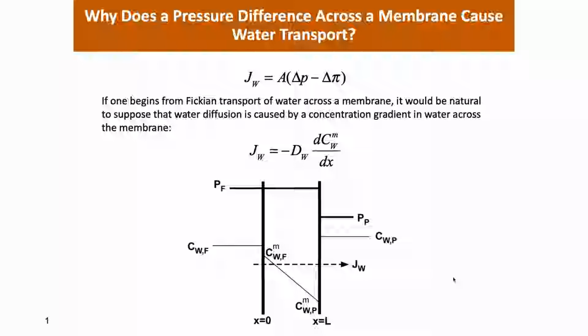And so there was the rise of a theory for reverse osmosis, or in general liquid transport through what I would call non-porous membranes, that was based on the principle that there must be pores in the material that would allow flow driven in the same way that pressure drives flow through a pipe.